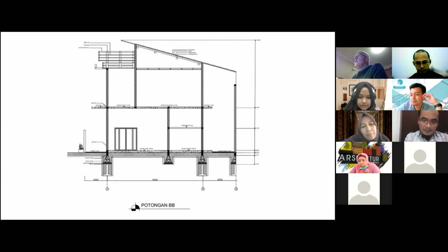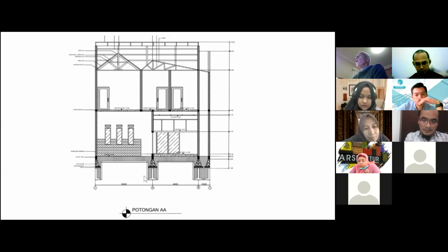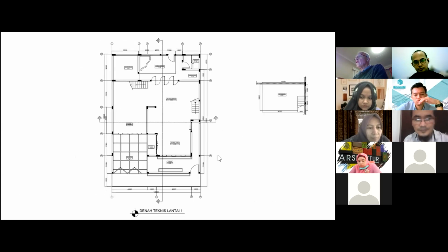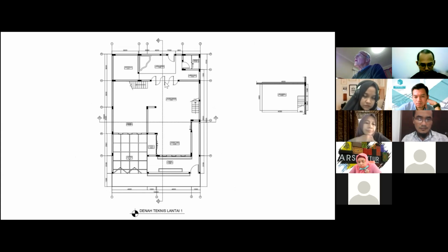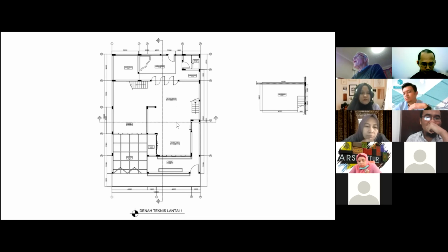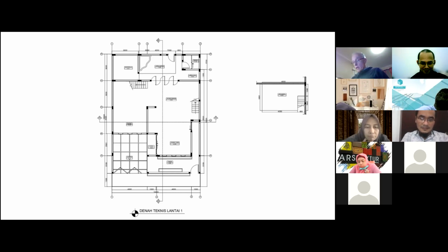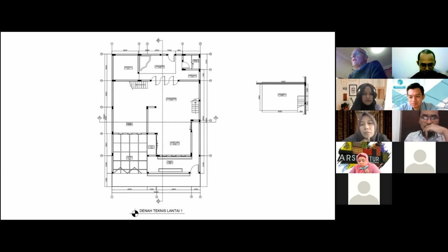Okay. So let's go to the floor plan. Well, we need to go to the ground floor plan. And so the floor slab, it has to span, well, we'll say the floor slab is spanning this way. It has to span about, well, it's more than 5 meters. So a floor slab spanning 5 meters, how thick, how deep does it need to be? It needs to be about 25 centimeters, doesn't it?